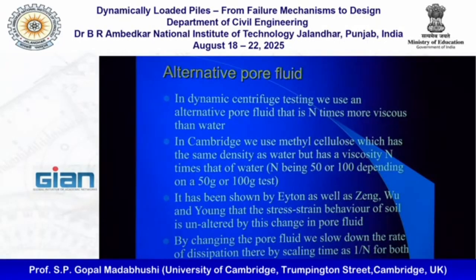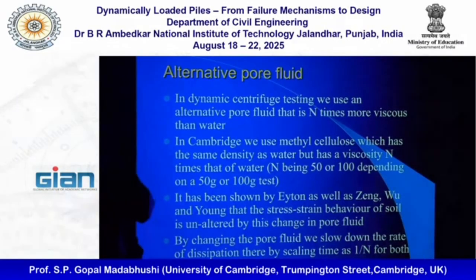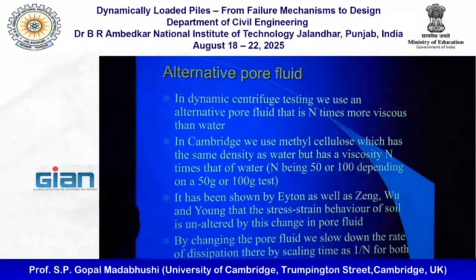And after the earthquake is finished, it will start to dissipate. So the rate at which it dissipates in the post-seismic period and the rate at which it builds up in the co-seismic period will match by doing this pore fluid substitution. Otherwise, the rate of buildup will be too quick and dissipation will be too slow. So we shouldn't be doing that.